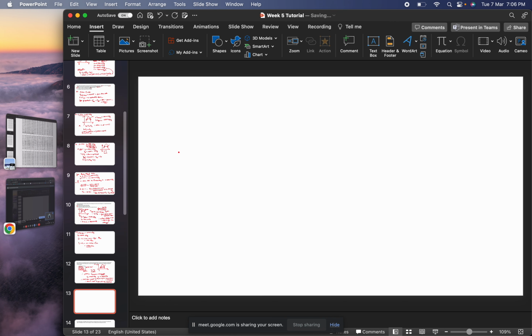Okay, now we know the total volume occupied by this one. So therefore we know that specific volume is basically total volume divided by mass. Okay, so therefore mass of the gaseous steam present is total volume occupied by the gas divided by specific volume of the gas. Okay, so we have found both.